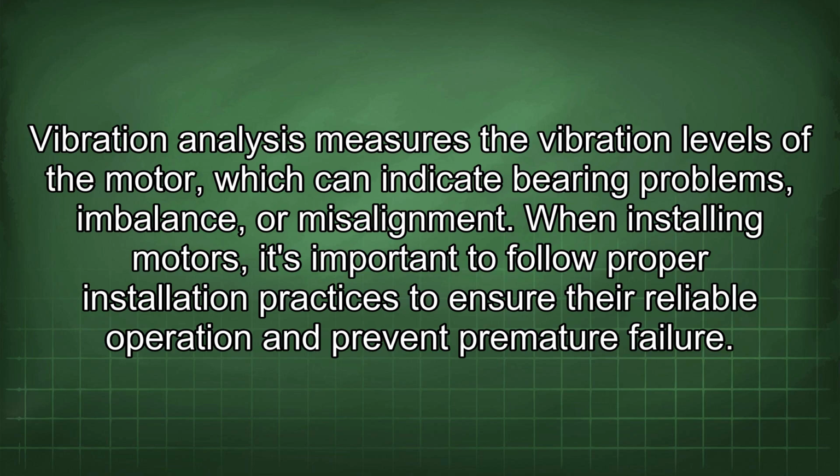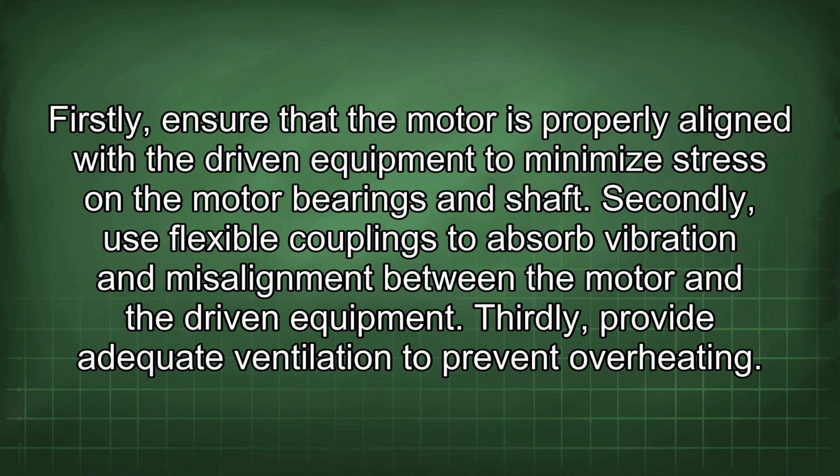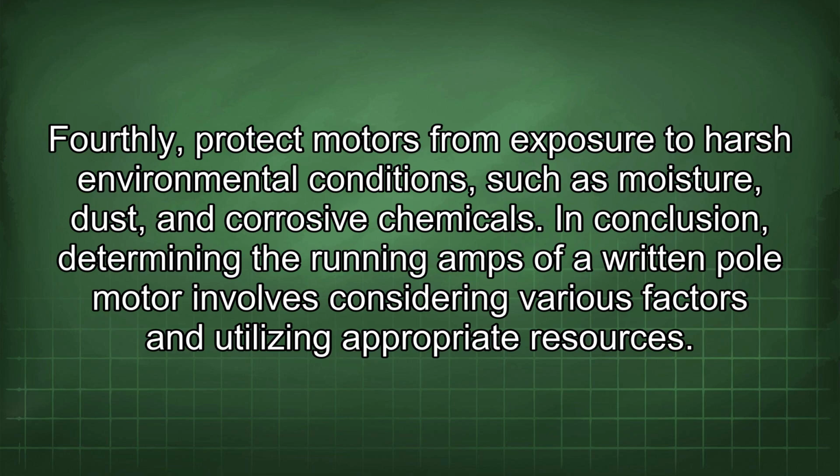When installing motors, it's important to follow proper installation practices to ensure their reliable operation and prevent premature failure. Firstly, ensure that the motor is properly aligned with the driven equipment to minimize stress on the motor bearings and shaft. Secondly, use flexible couplings to absorb vibration and misalignment between the motor and the driven equipment. Thirdly, provide adequate ventilation to prevent overheating. Fourthly, protect motors from exposure to harsh environmental conditions such as moisture, dust, and corrosive chemicals.